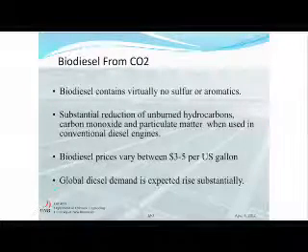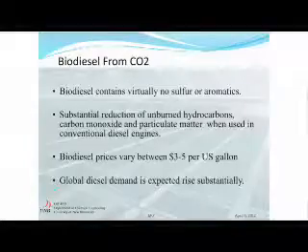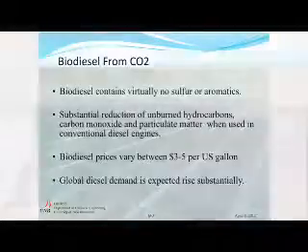Biodiesel as a fuel has many advantages. Firstly, it virtually contains no sulfur or other aromatic compounds which could harm the environment. Also, when used in conventional diesel engines, there would be a substantial reduction of unburned hydrocarbons, carbon monoxide, and other particulate matter.